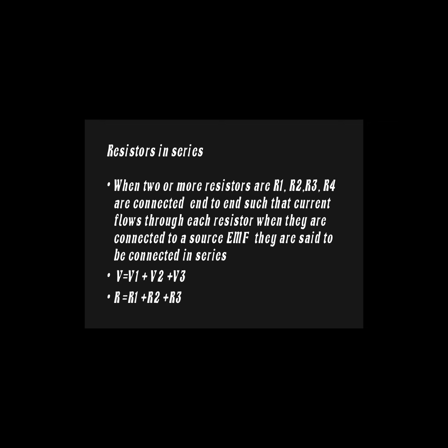Please, if you don't understand this particular thing I've told you, I want you to tell me. Because we make mistakes of, is it when we connect in series that current adds up, or is it when we connect in parallel? Students tend to make that mistake. But we should know that when we connect in series, the current remains the same and the voltage adds up. So in resistor 1, it has a voltage of 0.01, in resistor 2, it has a voltage of 0.02, in resistor 3, it has a voltage of 0.03, and so on.